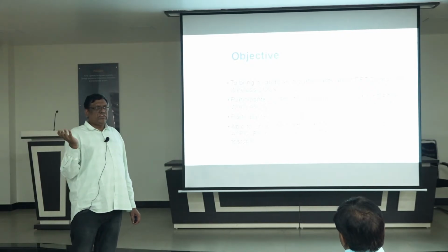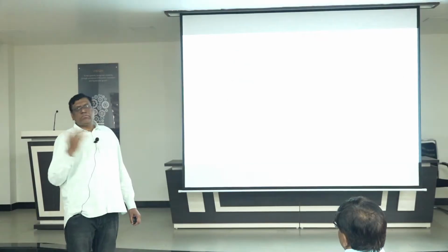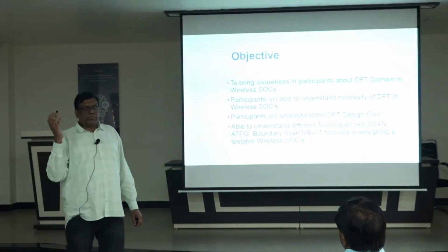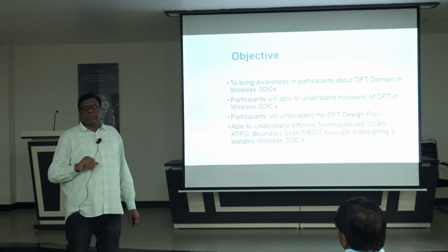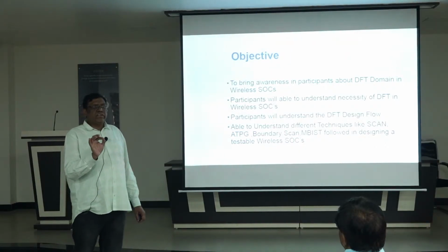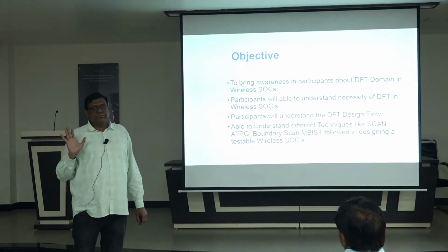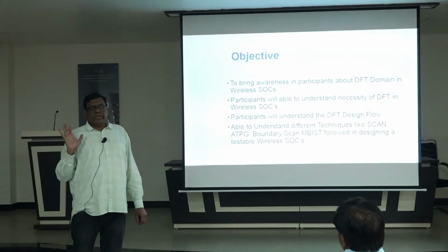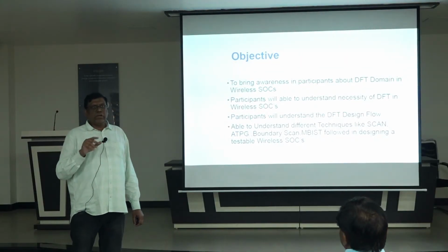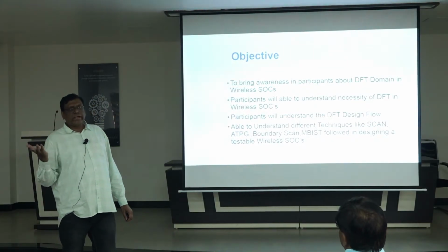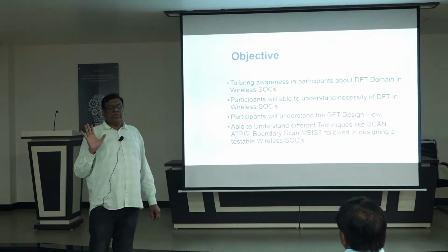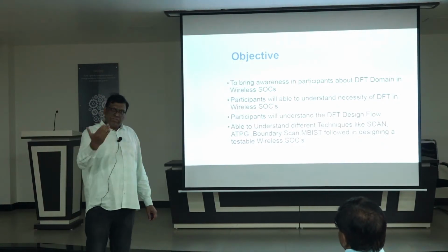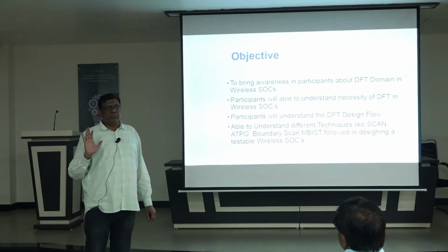Maybe in digital electronics you heard about so many flops: JK flip-flop, T flip-flop, SR flip-flop. But practically, in industry, they use only D flip-flops. Only D flip-flops, inverters, AND gates, OR gates, AOI gates, OAI gates. Only those things will be in the implementation, whatever your Kalman filter is finally converted into in RTL form.